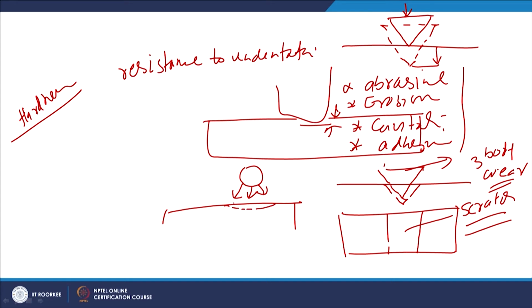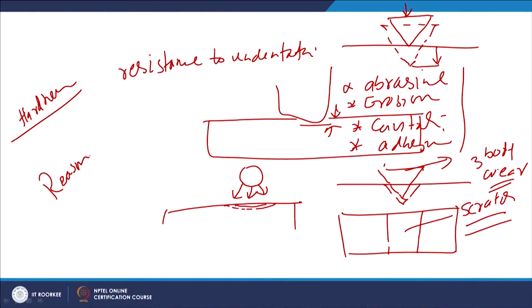If the material is hard, then it will not deform up to a greater depth, and in that case the chances for nucleation of cracks under the cavitation conditions will be reduced, and that is why it is important to have reasonably good hardness, not very high hardness, but reasonably good hardness, for cavitation, for adhesive wear, even for erosive wear.